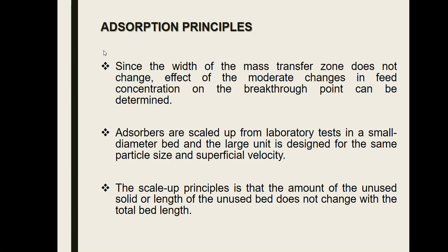Now, let's look into the adsorption principle. Since the width of the mass transfer zone does not change, the effect of moderate changes in feed concentration on the breakthrough point can be determined. Adsorbers are scaled up from a laboratory test in a small diameter bed, and the large unit is designed for the same particle size of adsorbent and superficial velocity that was used in the lab. Then the scaling will be based on the amount of the true fluid that will be processed in the plant. Okay, so small scale first so that it could be scaled up.